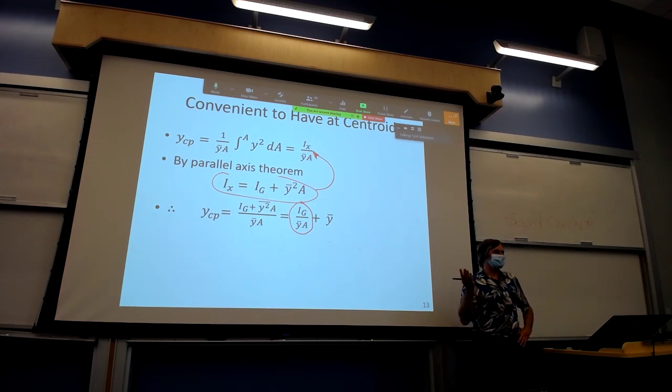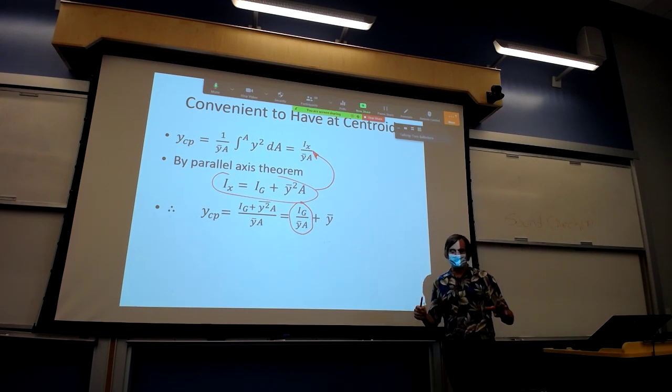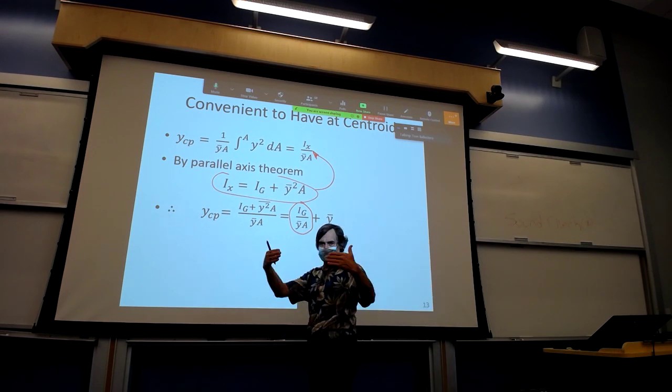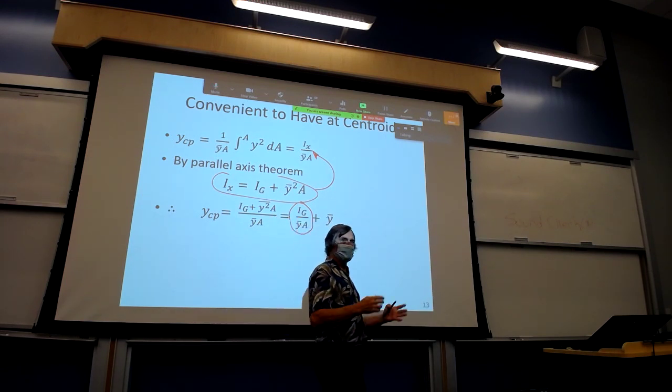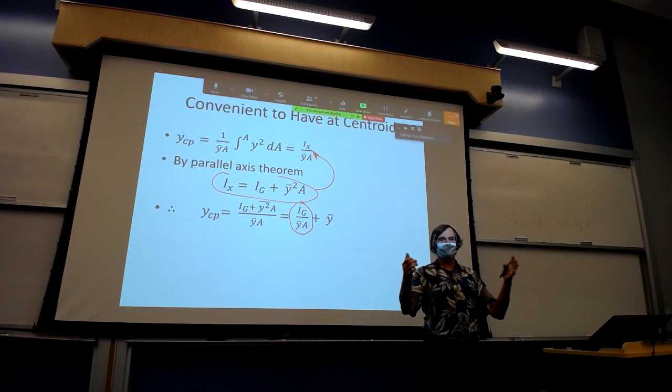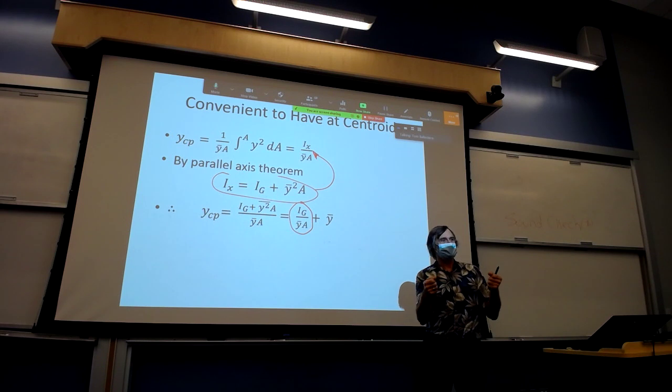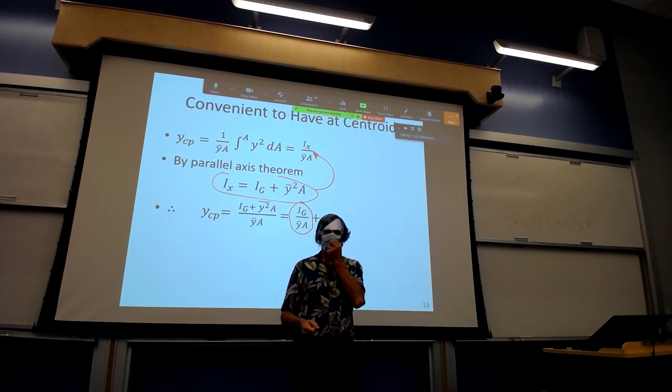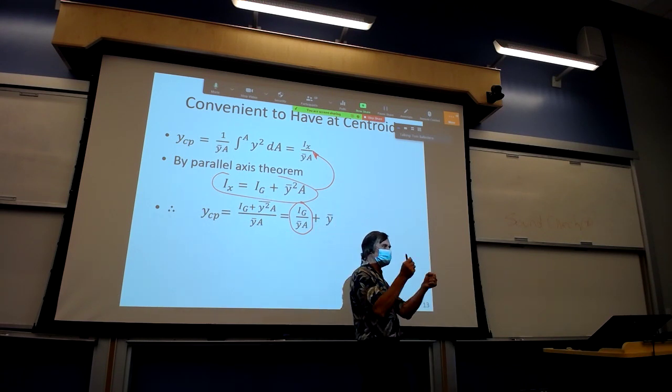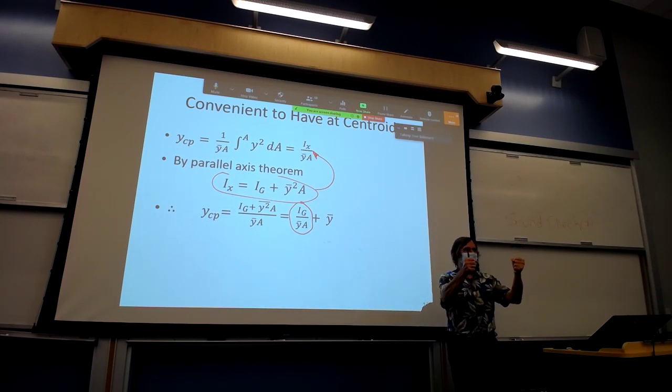Come on, there are two other terms there. IG goes to 0. Y is huge. Y bar is huge. So think about designing something. You're designing a gate that's going to sit under the water. Is that gate going to change size over time? Do you expect it to be changing? No. Therefore, its area and its moment of inertia are not going to change with time. However, what could change? Could you put this gate under deeper and deeper submergence?